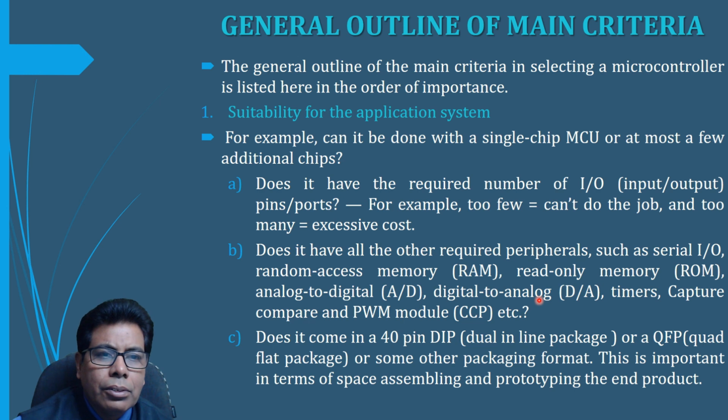Here we have listed these criteria in the order of importance. First is suitability of the application system. Here, whether the application we are trying to do is possible with a single chip microcontroller or a few additional chips, that is the first question.